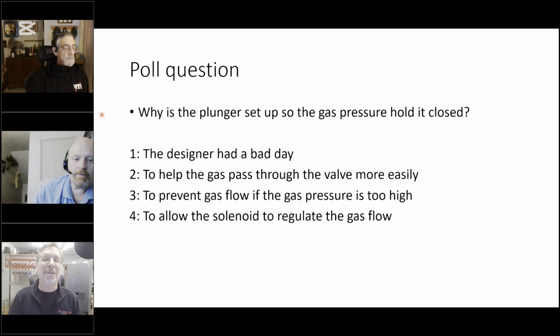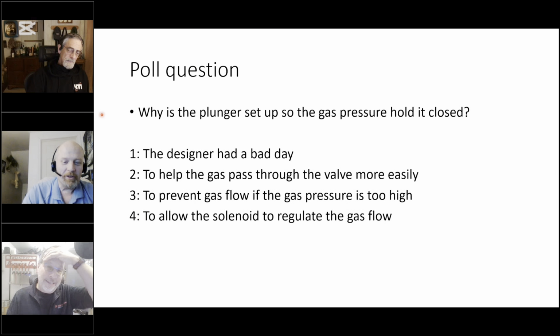Now, Mylek would like to know, when you had 40 inches of water column, did you do a combustion test on that unit? Well, the good news is the regulator was seeping. So as soon as it opened, the pressure regulated off to 7 inches and maintained. So I actually did do a test and it was okay, but within about 2 seconds of the valve opening, the pressure leveled off again.